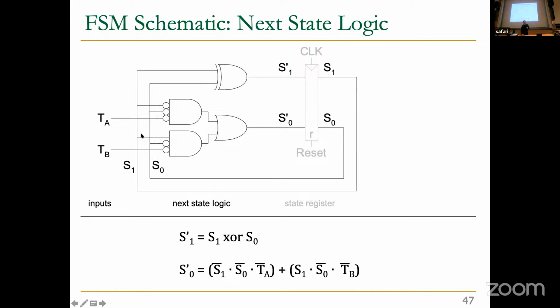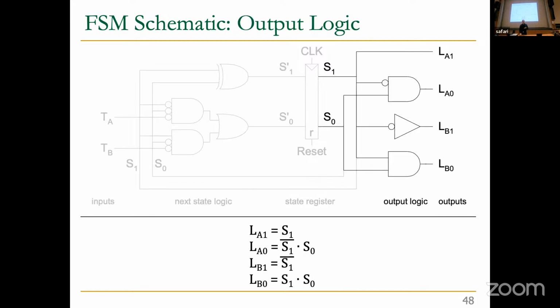Here, if your clock cycle is too short, you will potentially change the state to a wrong state, or you may not change the state because you didn't give enough time for the circuit to finish evaluation and get its output latched in the state register. Okay, now I introduced some timing into this, right? So far, we've been very logical, but timing is really important in these.